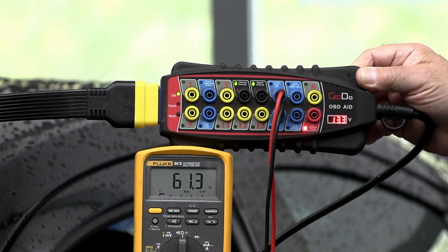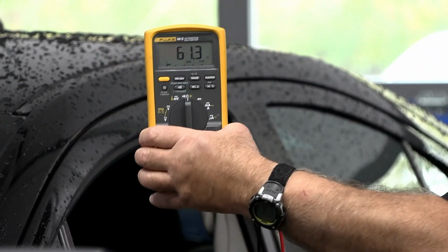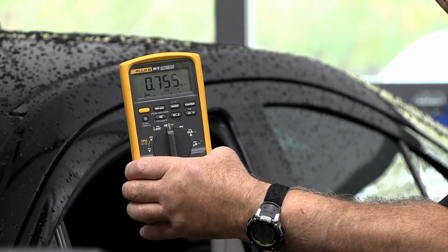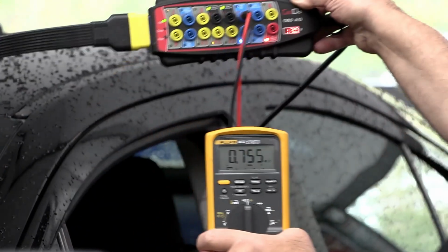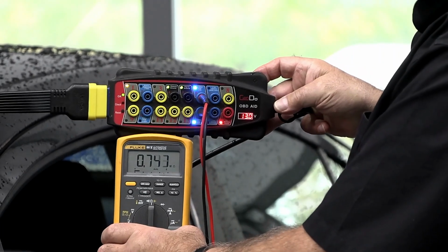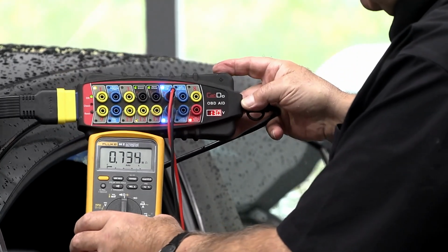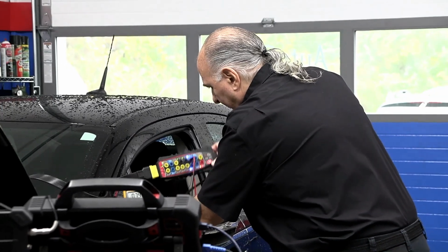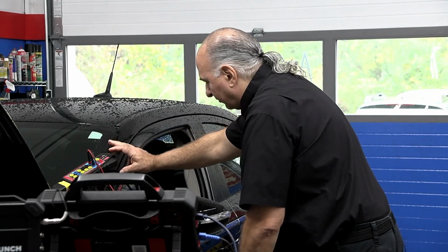Now watch this. I'm going to touch the door lock. Can they see that? Yep. What just happened? Do you see the bus came back to life? Do you see these blinking? So you don't want to test it with the bus on. You want to make sure it goes to sleep. And this will take a few seconds to go down. We're not going to waste the time here because we got to hook a scope up and a scan tool and take it from there.